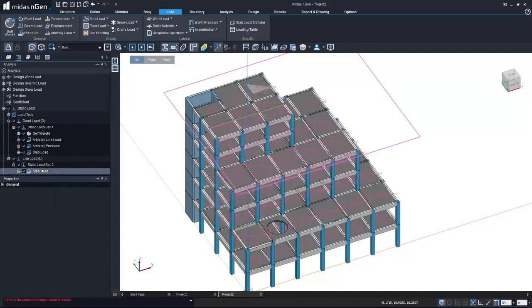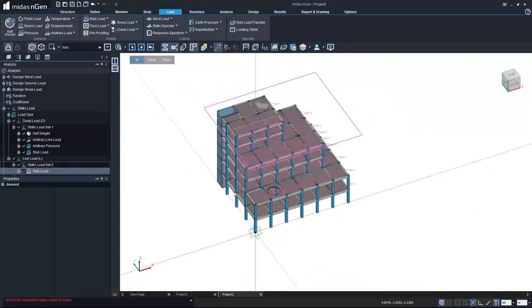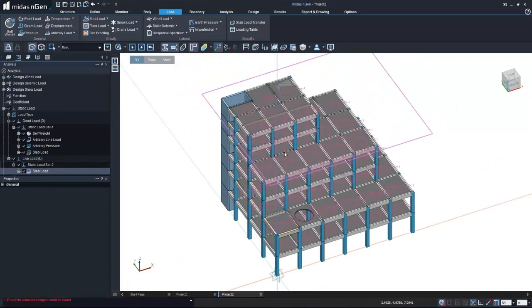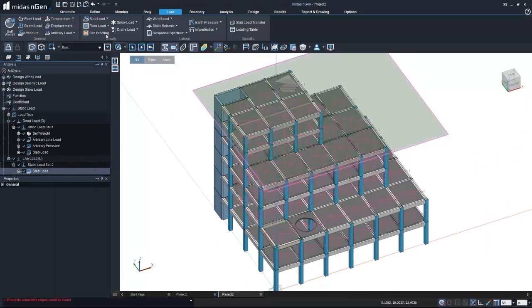So it becomes a kind of a tedious procedure when there are so many types of loads that you need to apply on the same slab. So I suppose this would become actually a faster way of applying the loads when it comes to slab loads. We also have got floor loads in case you do not want to model the slabs. So that's for the later discussion.